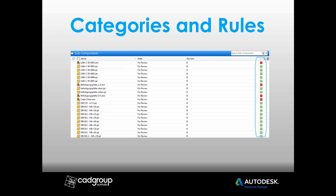Now, a little bit of a chat about categories and rules. When I talk about categories in Vault, categories are a powerful method of not only classifying different types of files, but they're a great way of automatically assigning other behaviors. So when you combine this with rules, as a user adds new files to Vault or migrates files from, say, Vault Basic, lifecycle definitions, states, revision schemes, revision levels, and specific properties can automatically be assigned to these files. This ensures a very high level of both consistency and completeness to the data.